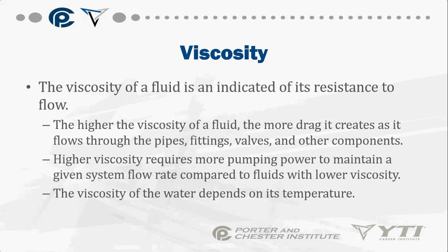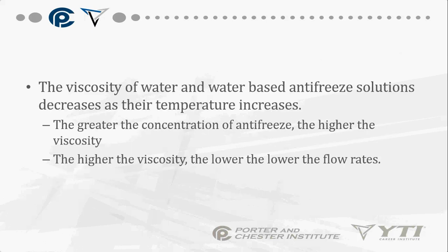The viscosity of the water obviously is going to depend on the temperature. Viscosity of the water and water-based antifreeze solutions decrease as their temperature increases. And the greater the concentration of antifreeze, the higher the viscosity. And the higher the viscosity, the lower the flow rate.